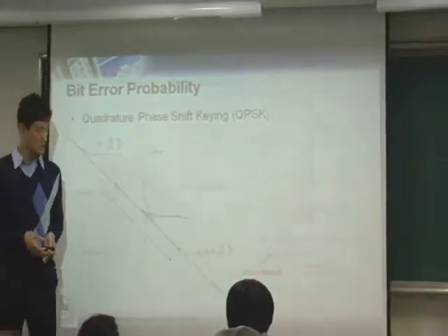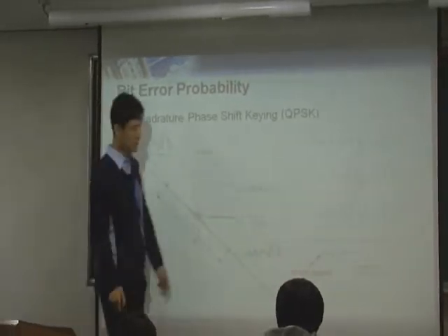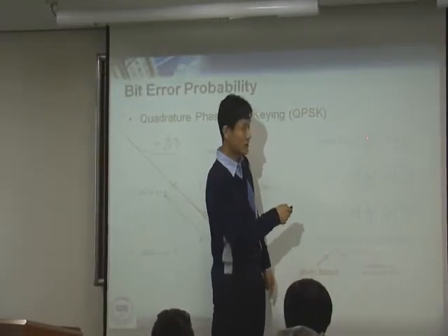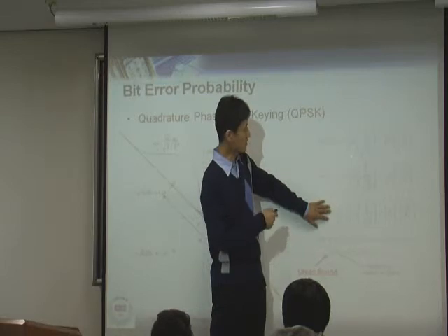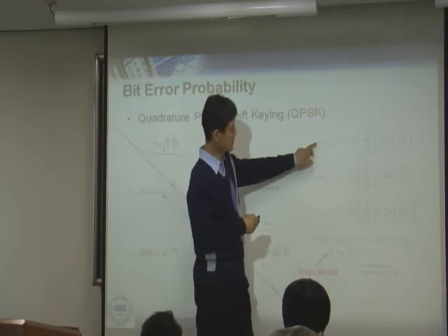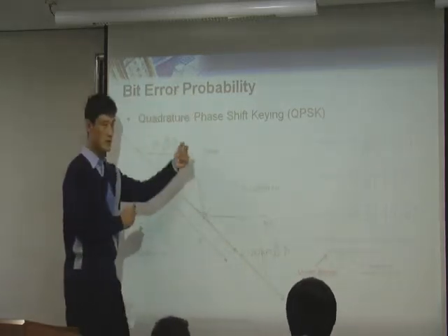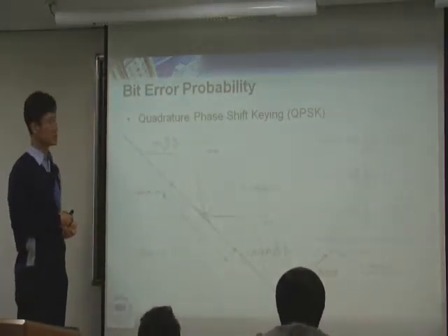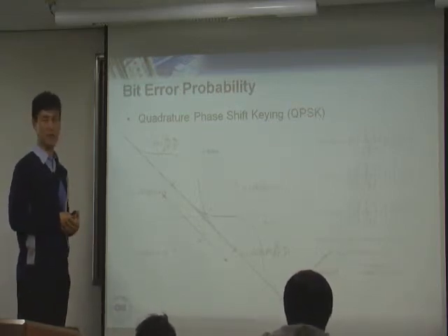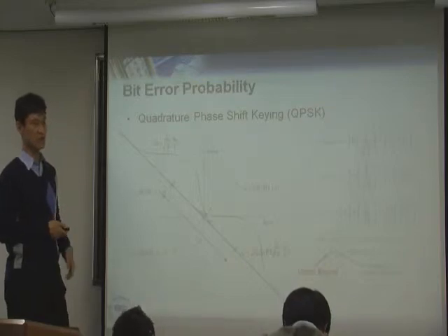So in this particular case, this is QPSK, so therefore you multiply 3. You multiply 3 with this case. What is this case? The first case. Among these 3 cases, the first case gives you the highest bit error rate, right? So you multiply 3 different cases, 3 times this one. So that's the union bound, okay? If you think about the high order modulation, this is the case of QPSK, but now think about 16 QAM or 8 PSK or any other higher modulations, they typically do this union bound to find out the bit error rate.